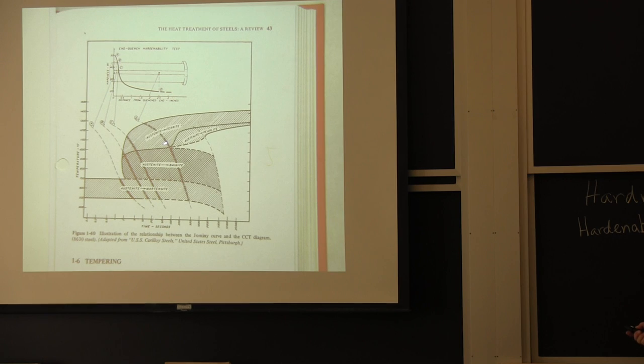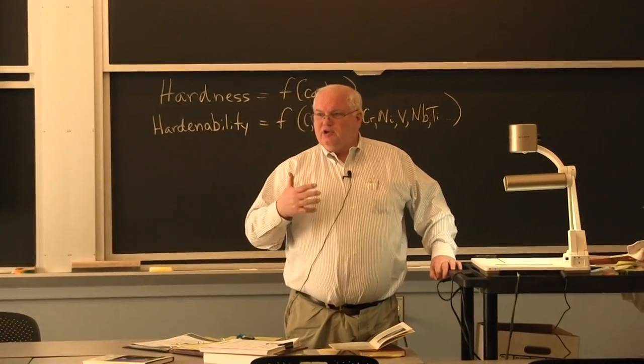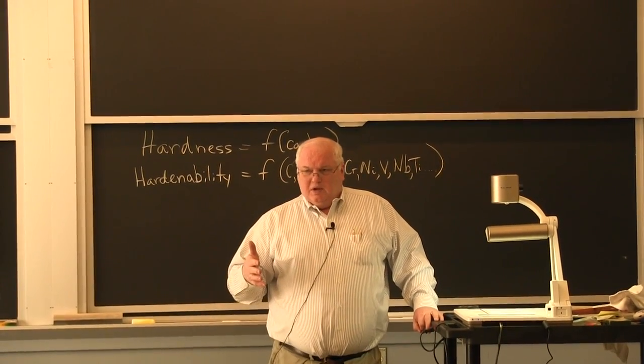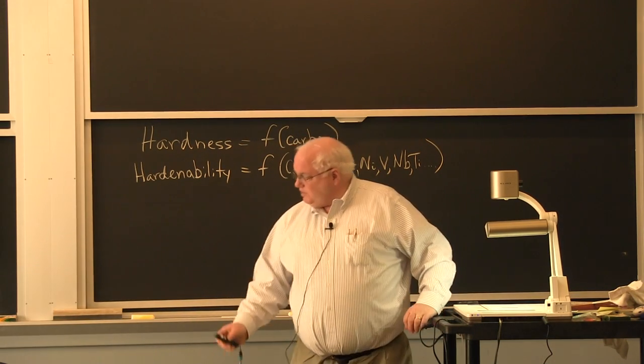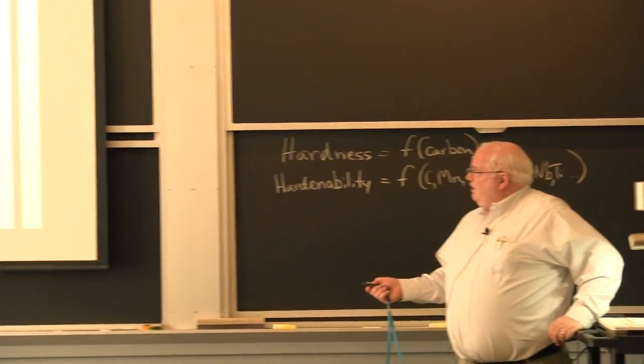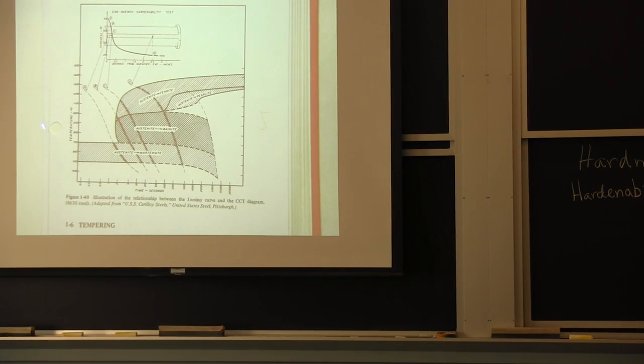You sometimes like to get bainite, but you're going to get a transformation when you weld, okay, in the steel, and that transformation can lead to excellent weld matching, so you can get the same strength as the base material. You can't always get that in, say, some of the aluminum alloys, but in systems that have a change in crystal structure from one crystal structure to another, such as the iron-based systems or the titanium-based systems, you can usually get matching strength between the weld metal and the base material. And so that's one of the advantages that the iron-based system has.